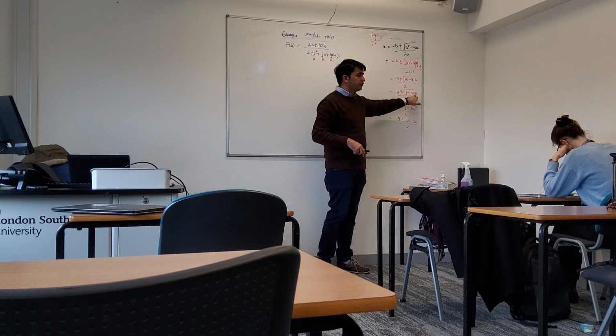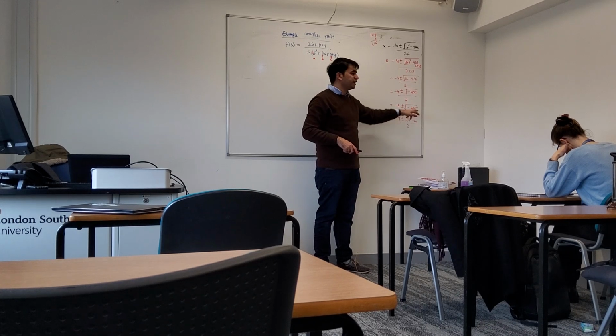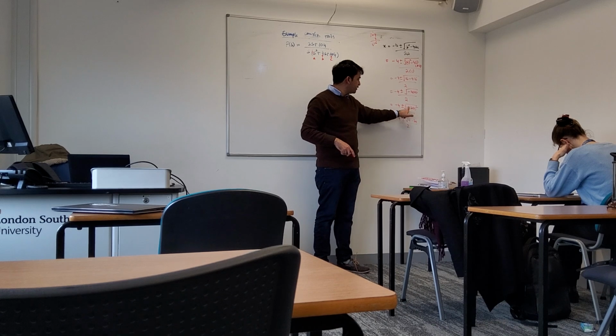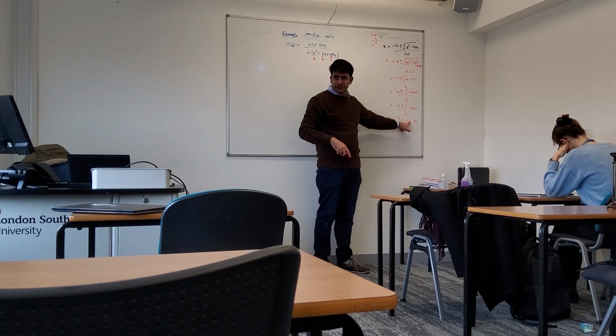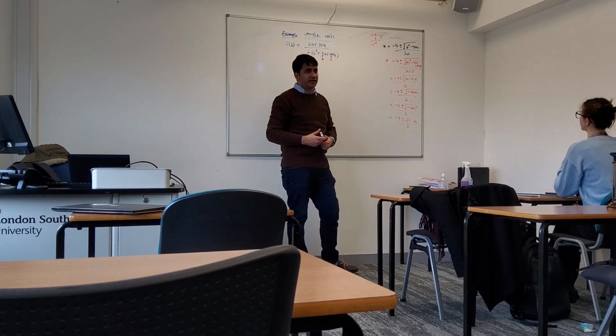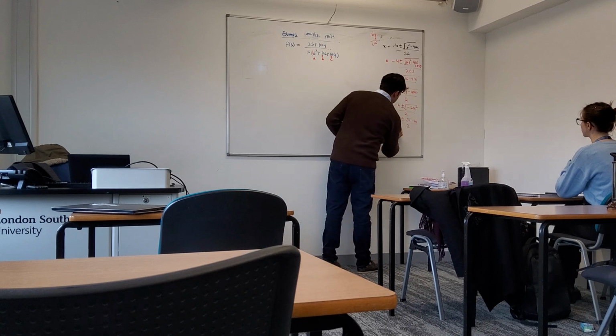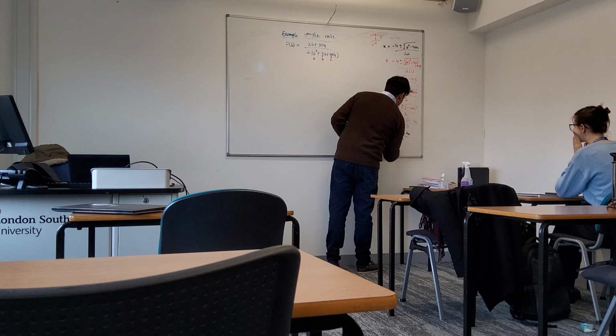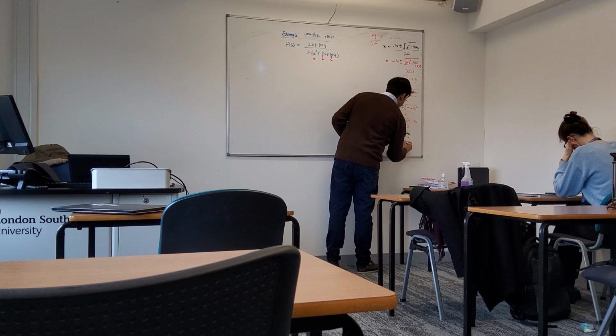We know that 400 we can write as 20 squared, but we still have a negative sign with it. So I can split it: under root minus 1 would stay, and for 20 the root and square would cancel, turning out as 20. So this would be minus 4 plus minus j 20 divided by 2, which is minus 2 plus minus j 10.